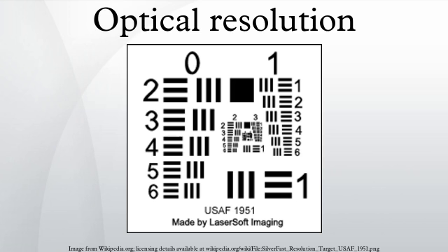Where the active area of the pixel has dimensions a by b, and the pixel real estate has dimensions c by d, in Gaskill's notation, the sensing area is a 2D comb(x, y) function of the distance between pixels, convolved with a 2D rect(x, y) function of the active area of the pixel, bounded by a 2D rect(x, y) function of the overall sensor dimension.